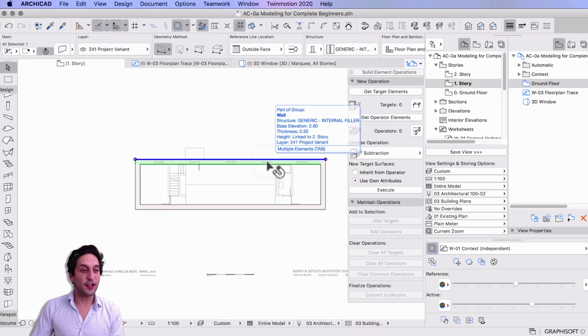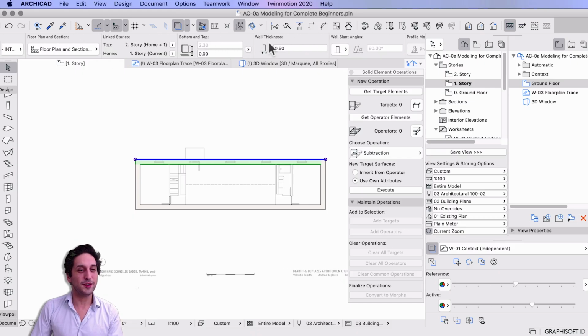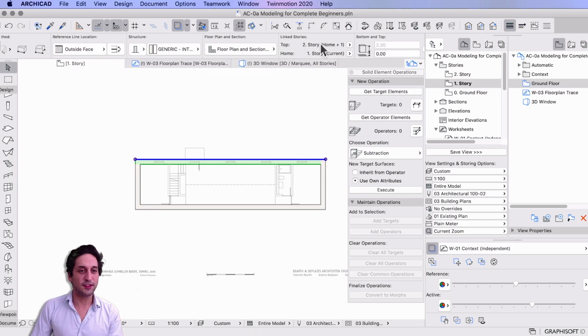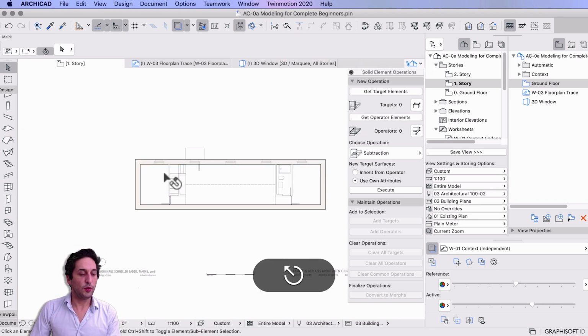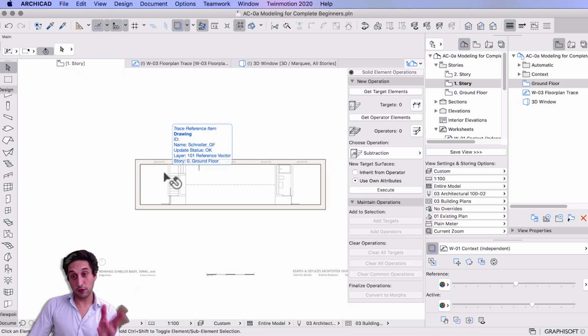Funny enough, when I show you how high it is, you're going to notice that it's no longer 270, it's now 230 high, because the height of the next level is set to that height. So when you go check the 3D, you'll notice how 2 walls that were the same suddenly have 2 different heights. And that is because it's hidden in the story settings, which we explained in a video that you can see in the script right now.